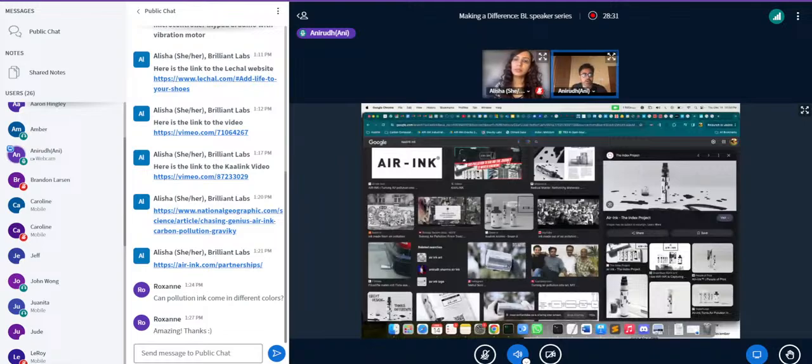It's virtually everywhere. Whenever you run a car, you will have it. You run a generator, you will have it. Your ships, your planes, they all produce it. These are very tiny particles, 1/70th the width of a human hair, 1 to 2 microns in size. The principle, in very simple language, is like when you take a comb and do electrostatic charging, you can pull paper with it like a magnet. The same way, if you produce electrostatic charge, you can catch carbon without exerting any back pressure on the exhaust stream.